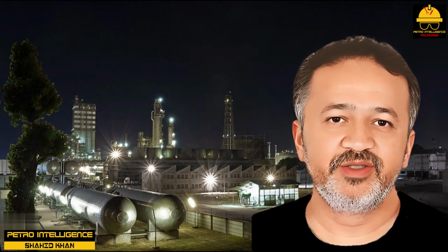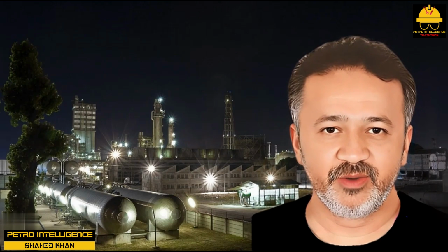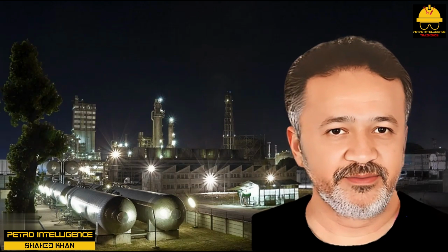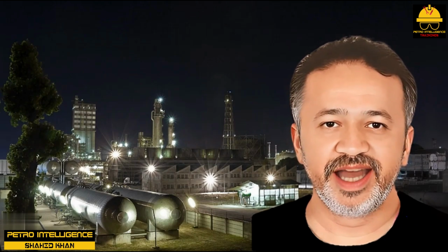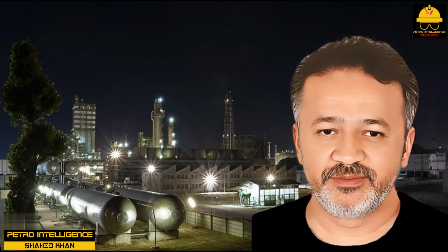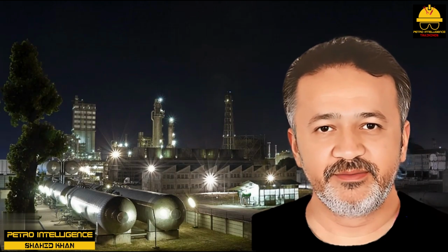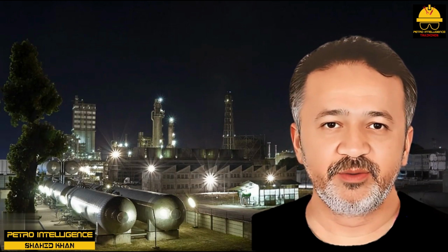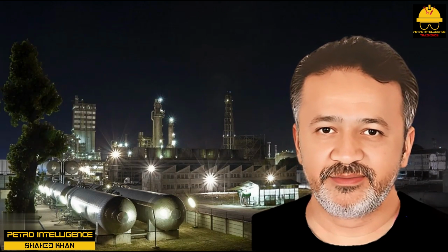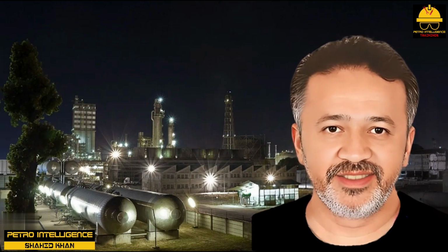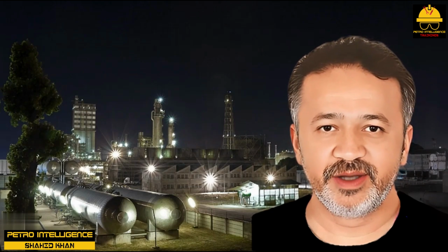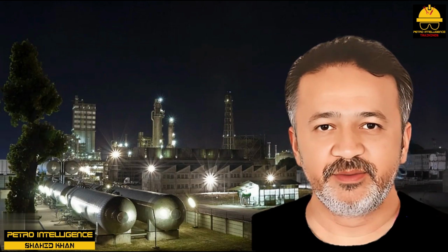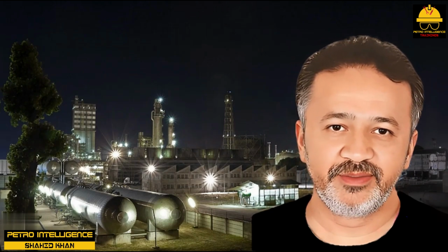An engineer had a similar, but less dramatic experience on a liquid-filled reactor converting propylene to viscous polypropylene, a gasoline additive. The catalyst was aluminum chloride added continuously with a small pump. The pump malfunctioned. During its outage, we failed to stop feed to the reactor. The propylene content of the reactor increased. Finally, they restored the catalyst flow, but the liquid-filled reactor became very warm, very fast. Fortunately, an alert operator stopped the propylene feed to the reactor in time.